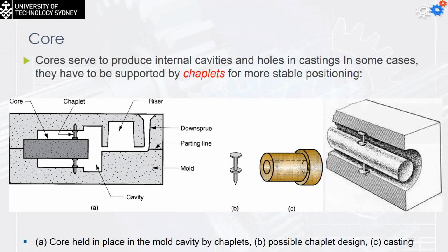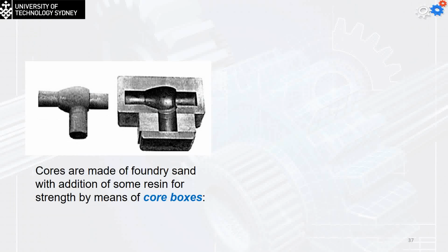So this is how to make the core. I'm going to have the core mold filled with the sand, with binding material, and I have to cook it. Just put it in the furnace so it's going to be solid enough to hold the high temperatures. So this is called the core boxes. I can make many of them, or I can make them as two halves, then stack them together to have complicated shapes.